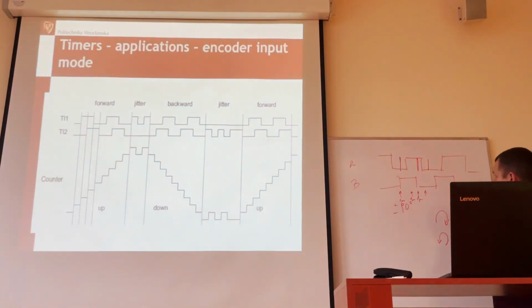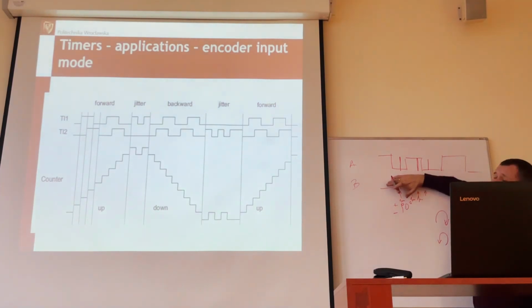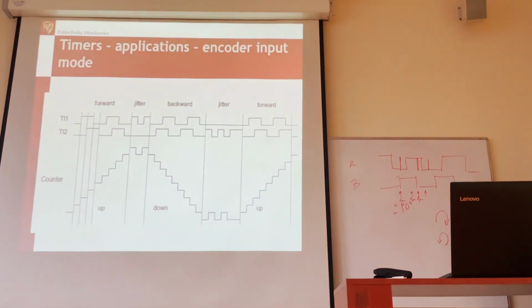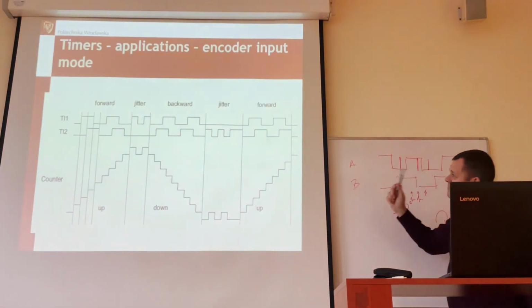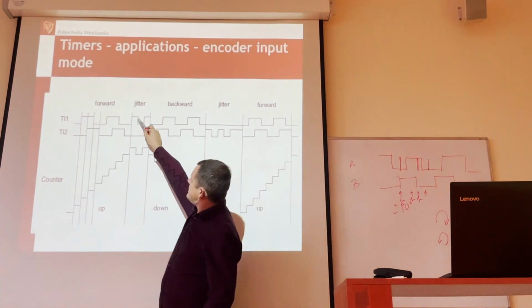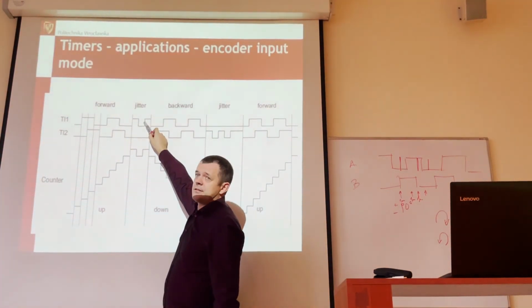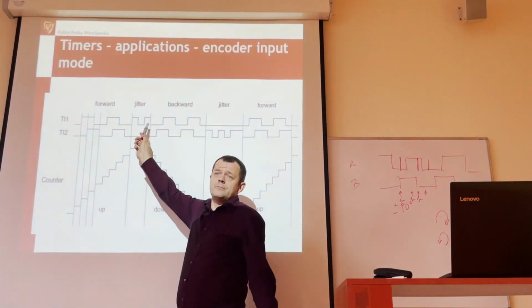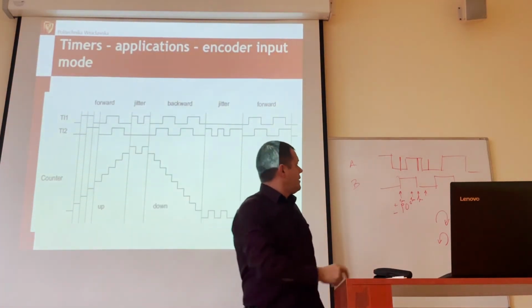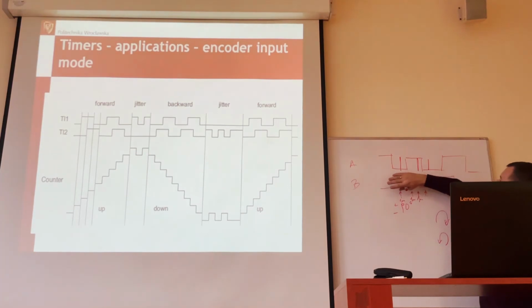Normally, if we analyze such a signal, we would count them up. We would include them in the final result. But for the encoder type signal, they are just excluded, because formally, if such a spike happens, this is calculated plus, this is minus, +1, -1, so this is 0. In a single lane signal, it's counted always.